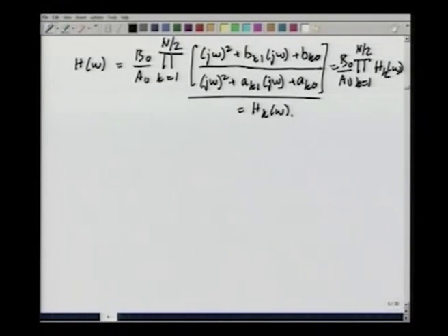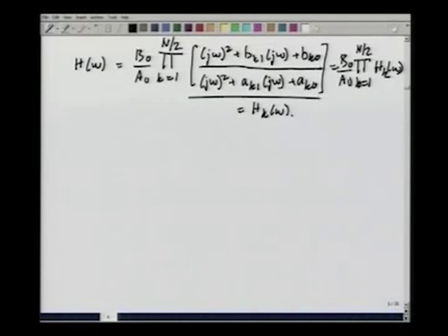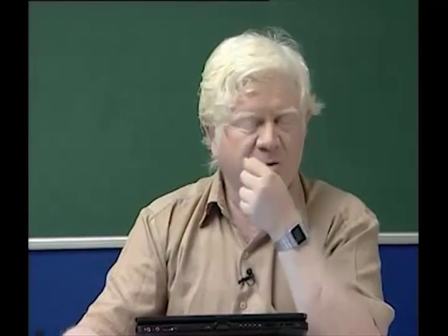Now, let us understand one implication of the convolution theorem. The convolution theorem said that if you applied x omega or x t to a system with an impulse response h t and got output y t, then y omega was x omega times h omega. From this it followed that if you applied y omega further to another system, say h dash with impulse response h dash of t, and therefore a Fourier transform h dash of omega, to get say z of t, then z of t would have a transform z omega which related to x omega and y omega as follows.